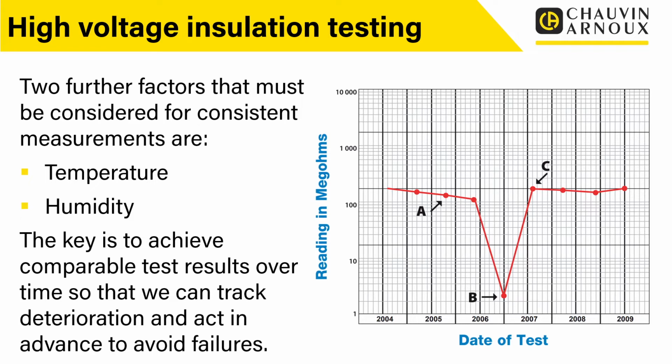So sometimes when we carry out a test, we may find that there's a problem with the insulation resistance due to humidity, but actually that's just a temporary effect. And once it's been dried out properly, then it's okay again. So it may be something that's reversible.